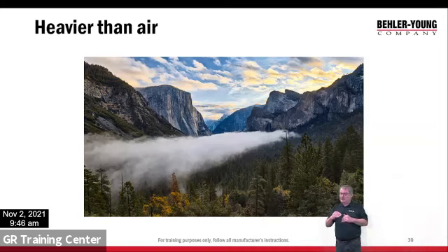So propane's not real bad, but gasoline is 4 times heavier than air. Every so often you'll hear somebody in their basement cleaning car parts with gasoline, and the water heater ignited it, because that gasoline vapor pools at the floor till we get enough of it, and boom.